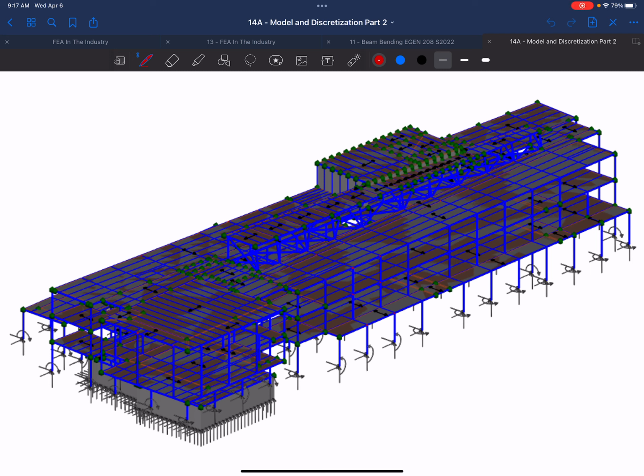How'd you permit that? Did you have to go through and graph every single member? No, I mean, they have member results, right? And it will relate all of the steel checks in the steel manual. And so it runs down and it gives you a unity check and it'll do combined everything. And it puts it on one nice little printout.